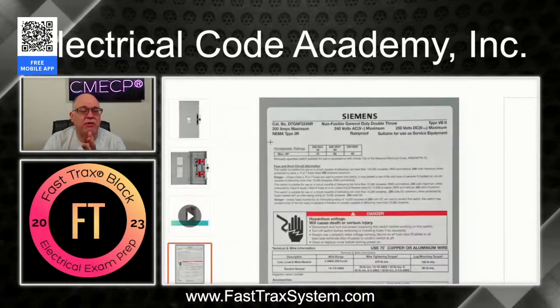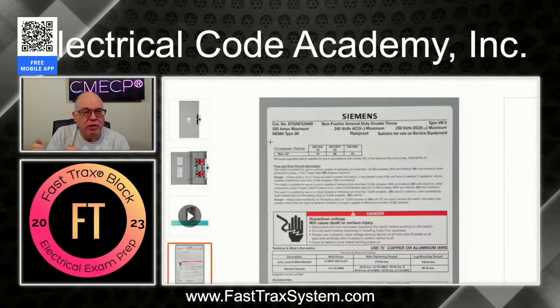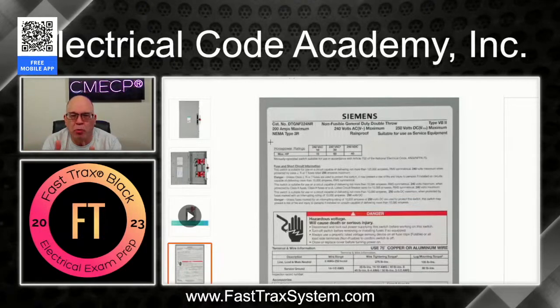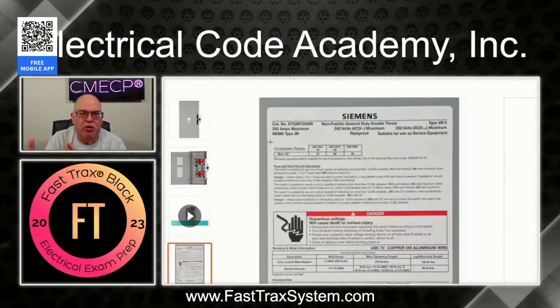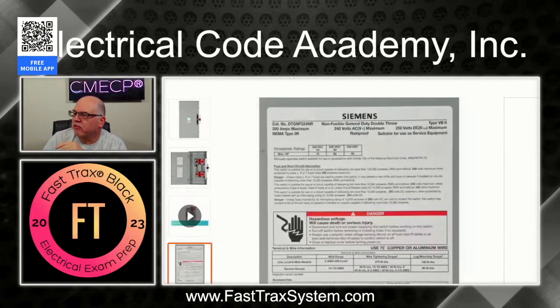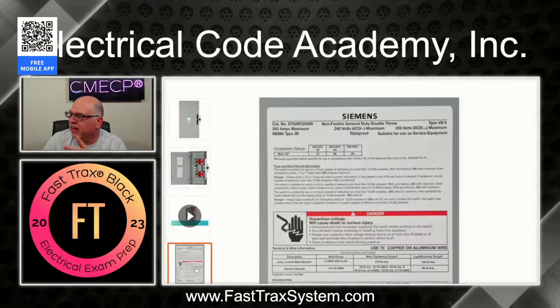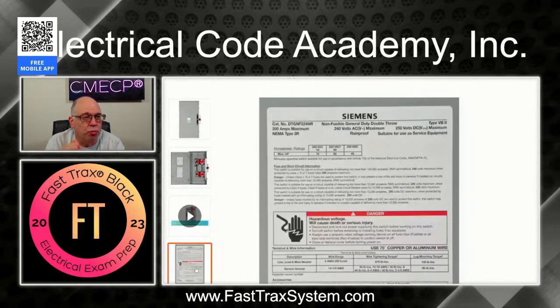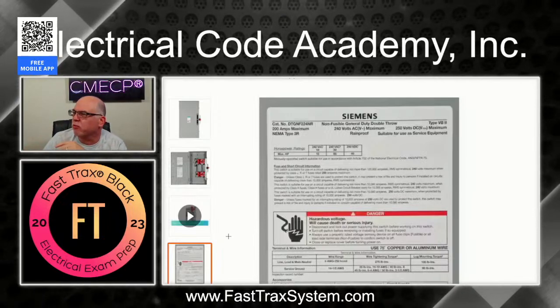All right, now, why is that important? Well, because that's what it said. I could use this switch. And remember, it's non-fused. So it's not providing any overload protection that's required by 230.90. It's just a switch. It's just the emergency disconnect. And so, again, that's what it kind of looks like inside. And that's all it's serving. It does not say on it anywhere that it's suitable only for use as service equipment. It doesn't say that. So I can use this one here.